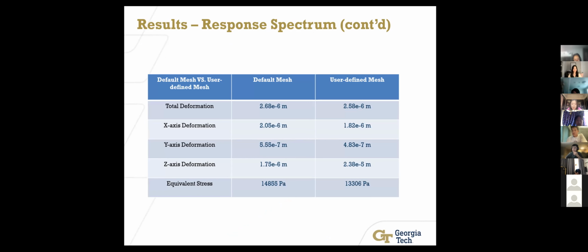And here's just the chart in which we compared the values we got for the default mesh and the user-defined mesh. As you can see, the numbers differ by a very small value, which is why this is the mesh independent study, and it shows that changing the mesh will not significantly change our output.